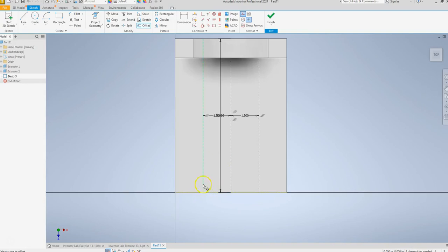And now we are going to come up 2 inches on each side. So let's go over to our line tool. Make sure the offset tool has turned off. We'll come down here at the bottom and we're going to come up 2, hit enter, and then escape, and then choose your line tool again. Make sure that it turns green so that you're in the center there. Type in 2, enter, and escape.